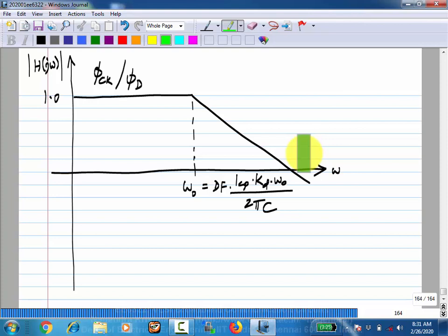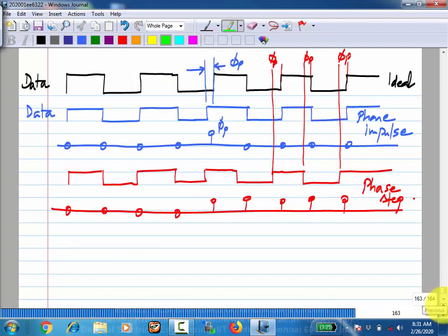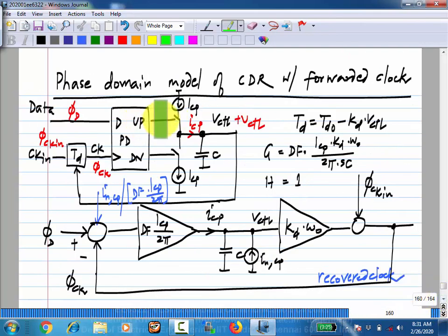So this kind of time domain visualization is very helpful and important. This detects the phase, and then that has to charge the capacitor. So let's say it measures the leading phase, it has to charge the capacitor, it will charge it by a little bit, and then it will move the phase by something. That phase may not be exactly what you want, so it may have to move it by further. So if you give it enough time, it will eventually track the input phase. On the other hand, after the first cycle, it corrects it. Let's say this phi d has gone, I mean the edge location has moved rapidly in the other direction, then obviously this tracking will not be correct. Is this okay? So that's the meaning of this low pass stuff.